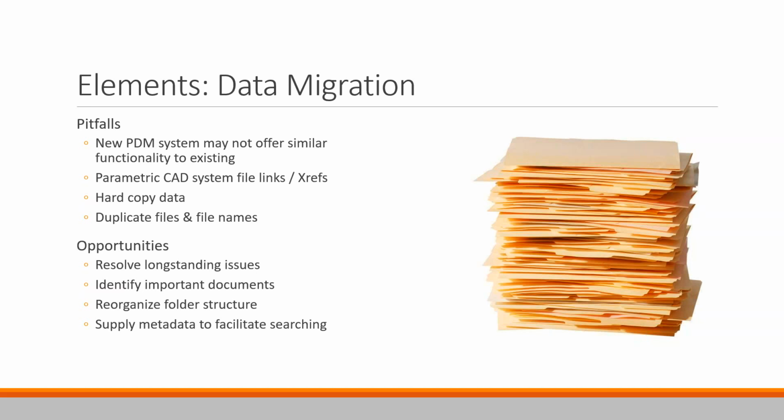And when that happens with duplicate file names, you end up with a lot of issues of Inventor asking you, okay, I found 10 files called bracket. Which one of these files do you want me to use when I open this assembly? So if you're using something like Vault from the get-go, you can tell Vault, I want all my file names to be unique. It won't let you check in duplicate file names, and so that's great. Windows folders, there's no such restriction.